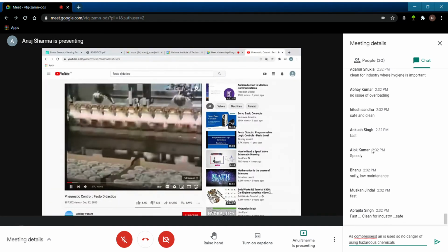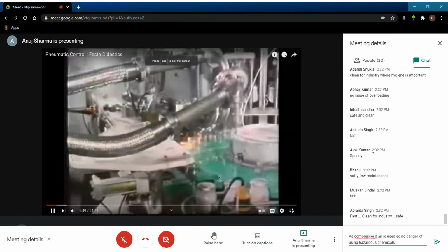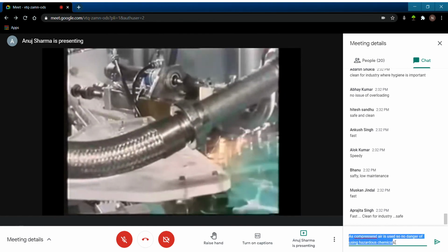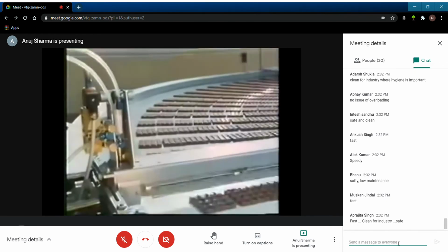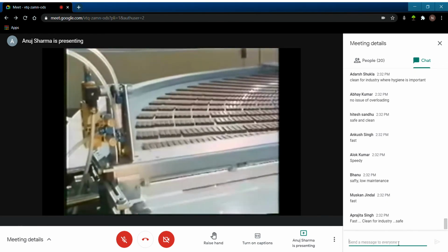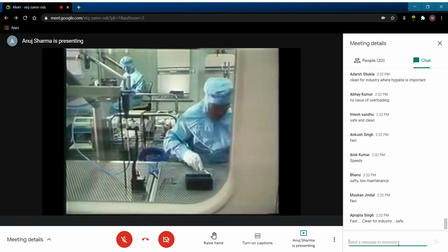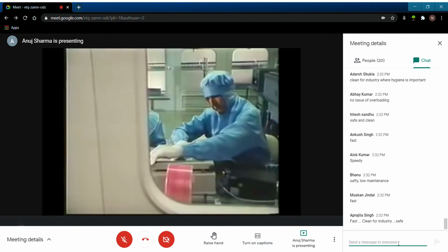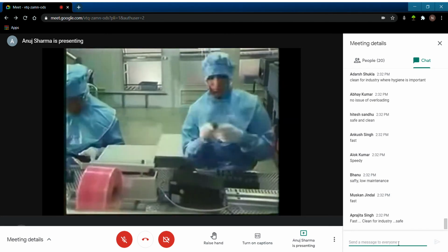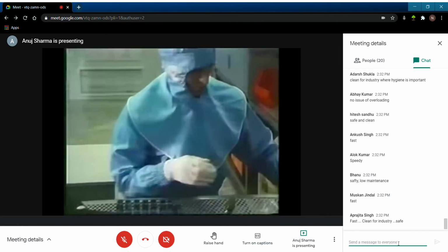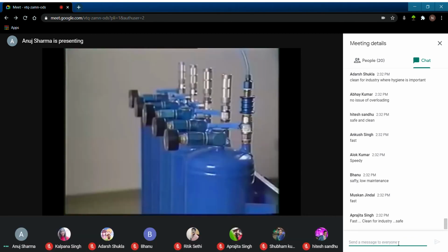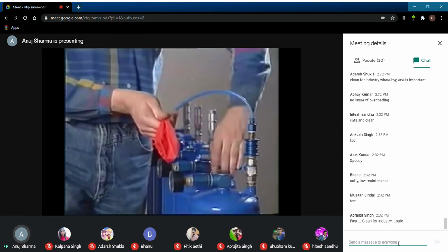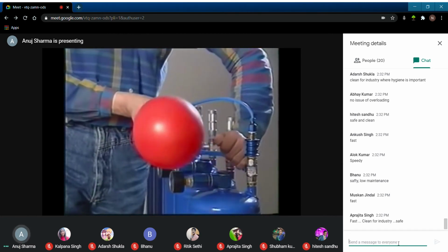Pneumatics is also safe because compressed air does not burn or explode under a wide range of operating temperatures. In addition, the exhaust air can be discharged directly into the atmosphere. Pneumatic systems are heavily utilized in cleanroom applications for the same reasons of cleanliness, low combustion, and fast operating speeds. Compressed air can also be stored, ready to be used when required.